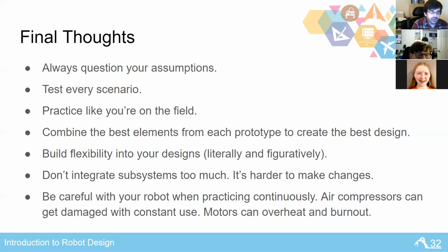It needs to not break. And in order to not break, sometimes that means you want your mechanisms to be able to flex so they absorb the impact, as opposed to something being super rigid, getting hit with a force that it can't absorb. And when that happens, it'll just break. Maybe it doesn't break the first 10 times that it gets hit, but it breaks that 11th time.